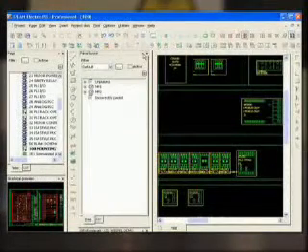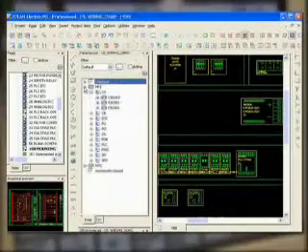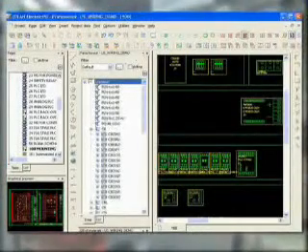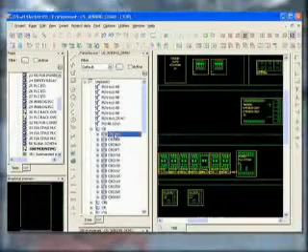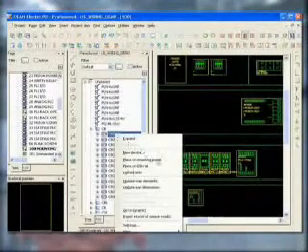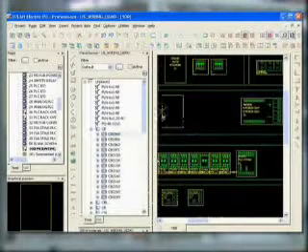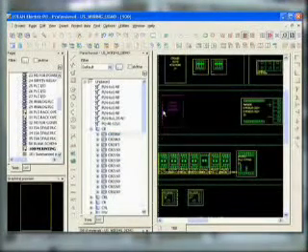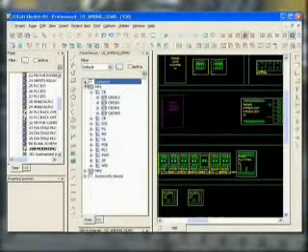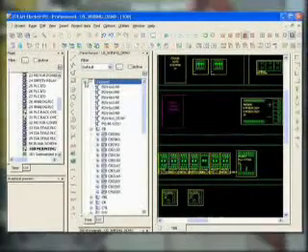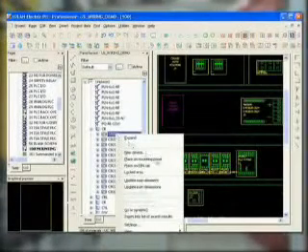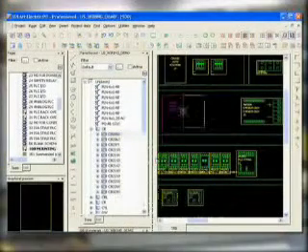With the Panel Layout Navigator, you can see all the components placed in a panel, as well as part numbers that are unplaced. To place a component, select Place on Mounting Panel. Select where to place it. It's moved out of the Unplaced list and into the MP1 panel in our example. The component can also snap to existing placements.